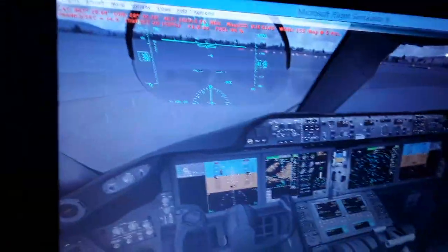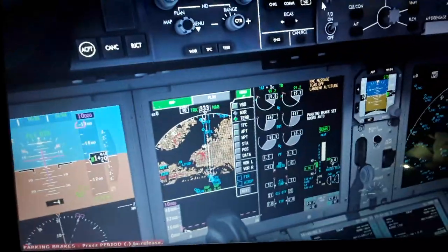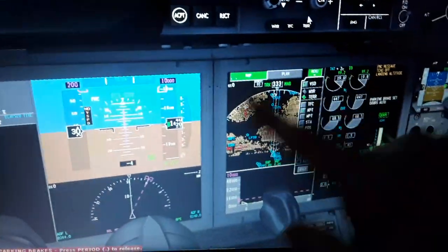I'm going to show you in a couple of minutes how I create it. We select the waypoints that will be connected with the purple line, and the aircraft can follow automatically if we need, using the autopilot flight director system panel for vertical and horizontal guidance, or we can fly the flight plan manually as it is displayed in the navigation display, both horizontal and vertical. Over here, as you can see, we have the horizontal profile and the vertical profile.